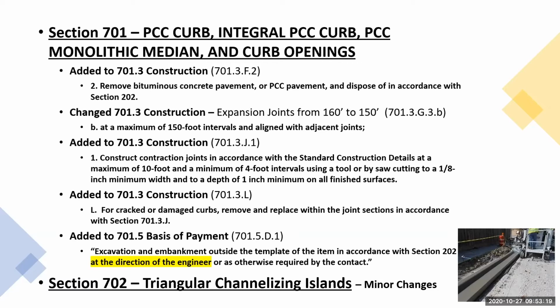And the basis of pavement, excavation embankment outside of the template. So any of the excavation embankment inside of the template will be the same, but if it's outside, it's highlighted that it's at the direction of the engineer. So it will only be paid if the engineer directs it. It's not within the template.